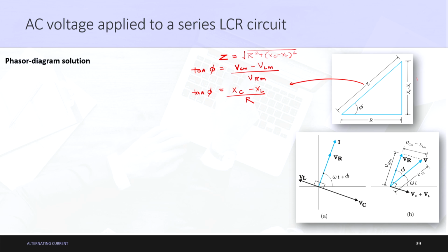So, what were the two different things which we required? We required I equal to Im sine of (omega t plus phi), correct. What is the value of Im? Im is nothing but equal to Vm by capital Z, where capital Z is impedance, and phi is equal to tan inverse of (Xc minus XL) upon capital R. I hope this complete solution is clear to you.